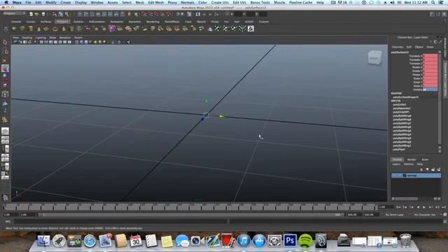Now, right away, you tap S again to record this on frame number 1, and if I go over the timeline and start to play it manually, you can see that in frame number 20, those faces are appearing. So basically, that way you can control the visibility of an object, and when you want the visibility to appear. Now, from here, we can start to animate this object in many different ways.